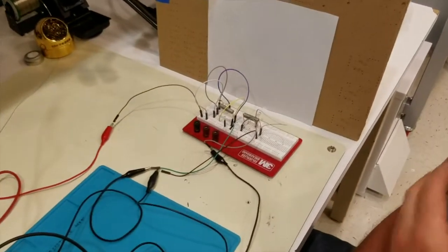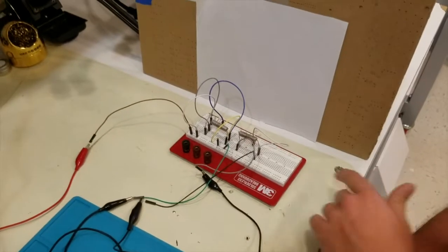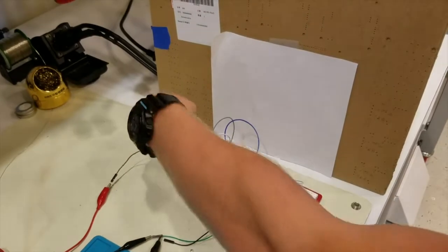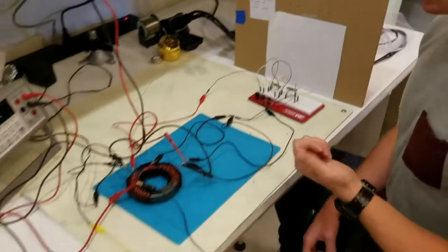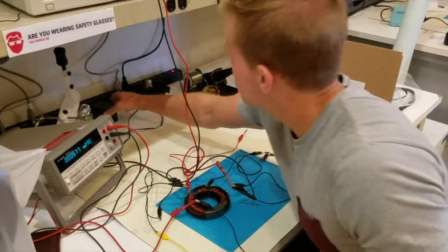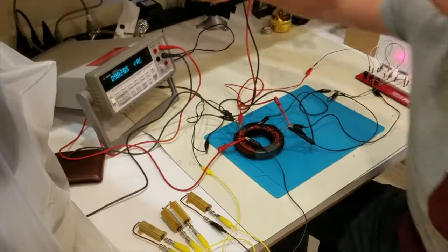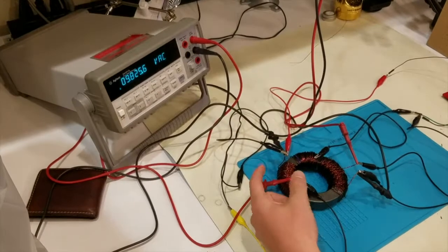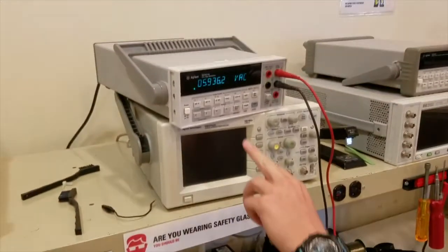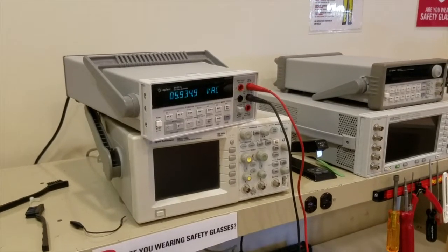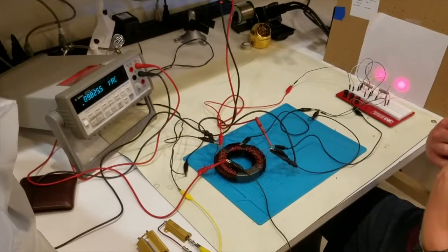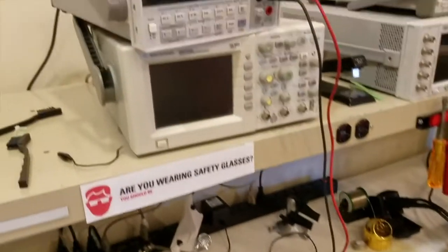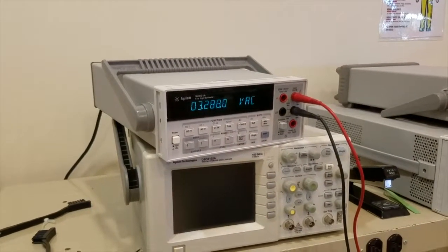Now, to demonstrate the drop in voltage from our primary to our 2 secondaries, we have an LED wired to our 100 turn secondary and an LED wired to our second secondary, which is 60 turns. Now, to show the voltages that are being dropped, we have 10 volts roughly on the primary side. We have 6 volts on the 100 turn secondary, and now I'll switch the voltmeter over. So now I have the voltmeter on the second secondary. We have roughly 3.3 volts here.